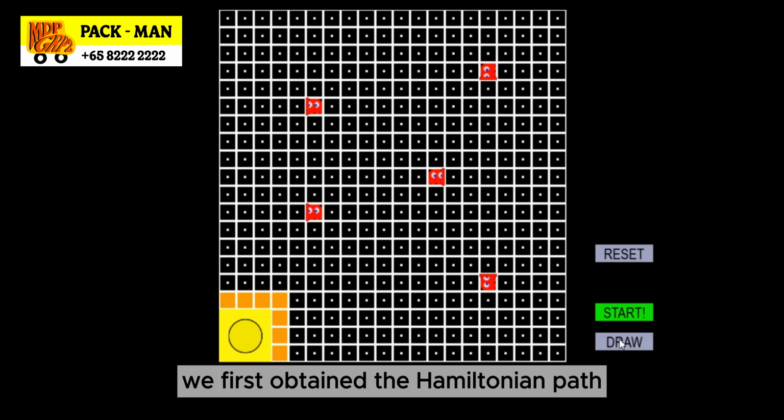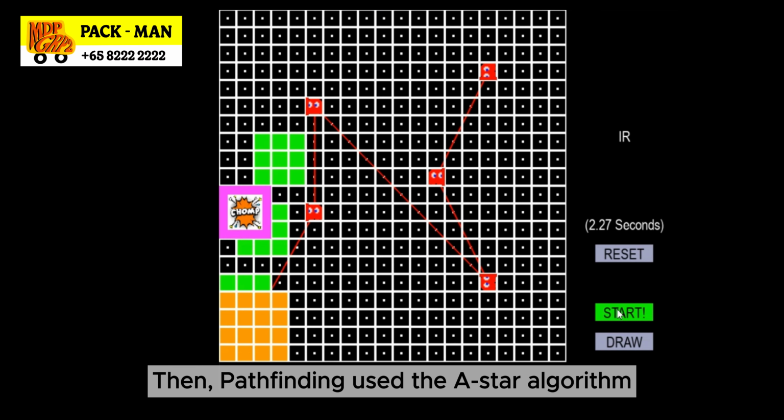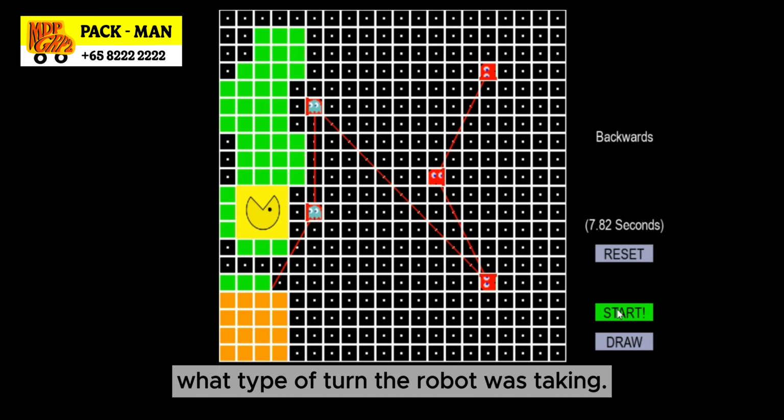For the algorithm, we first obtained the Hamiltonian path for all obstacles via a brute force approach where all possible paths were generated without picking the one that was the shortest. Then, pathfinding used the A-star algorithm with a heuristic of the Manhattan distance between current and end tiles, and the cost was modified by what type of turn the robot was taking.